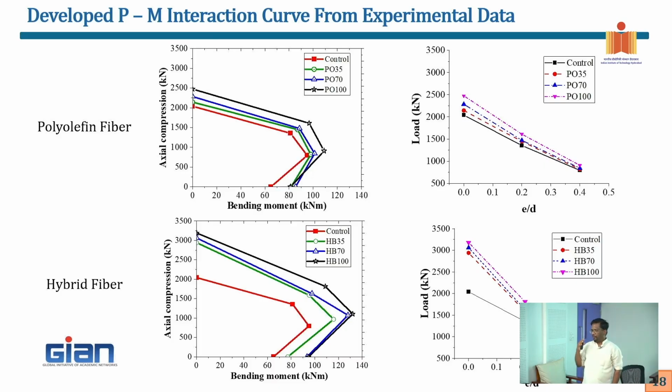So we said, if you really want ductility, strength, and multiple benefits, don't just add plastic fibers, you also add some steel fibers. So with mixing, you don't have a problem. Fire resistance you address, and ductility is also addressed. So that's the whole essence, right?